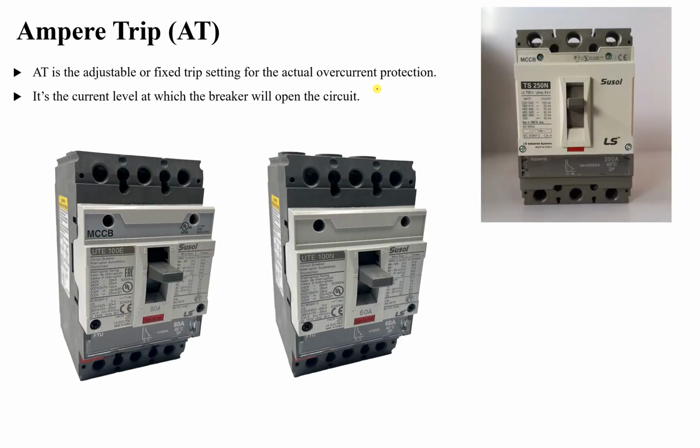So let me explain this. So these are three circuit breakers. If you look at them, you will find that this is an 80 ampere. So this is the current at which it will start to activate. So if you remember, a circuit breaker curve would be like this. It will have the overload curve, and then it will start having its own short circuit region like this, at which it will start operating quickly.